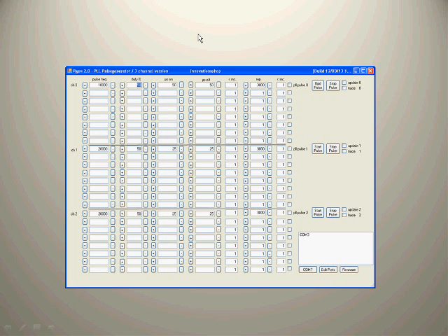Compared to hardware PLLs, those hardware PLLs are dependent on continuous pulsing. If pulsing stops, hardware PLLs, for example the 4046, lose the PLL lock and must re-establish the PLL lock after gating has stopped or gating has finished.